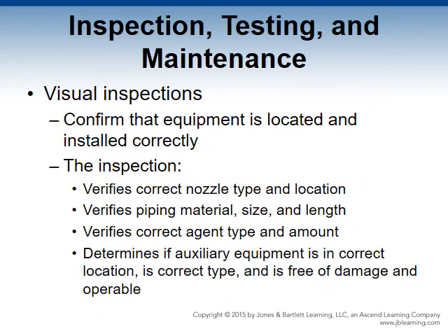After installation, extinguishing systems must undergo acceptance, inspections, and tests to ensure performance. The requirements are laid out in NFPA 17 and 17A. The process is simple for both kinds of systems, but many interconnected systems require appropriate operation for final acceptance. As with any system, periodic inspection, testing, and maintenance are required to maintain system integrity. Some inspections can be done by the facility maintenance staff, but others require trained personnel.